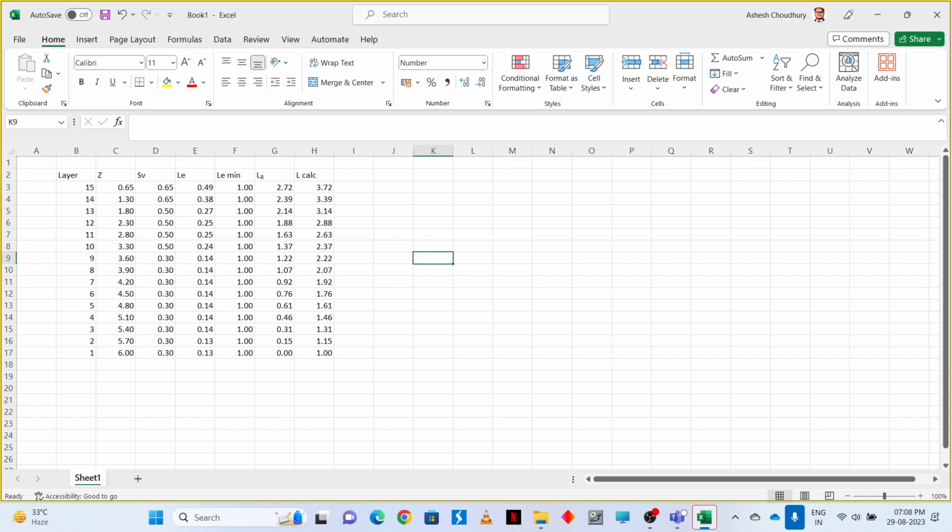Now up to some height we can provide one length, and up to other height we can provide another length, so we can subdivide. Providing different length for each layer is difficult, because you need to measure and cut the reinforcement for each layer. So we divide the complete wall into some blocks, and we fix the length for each block.